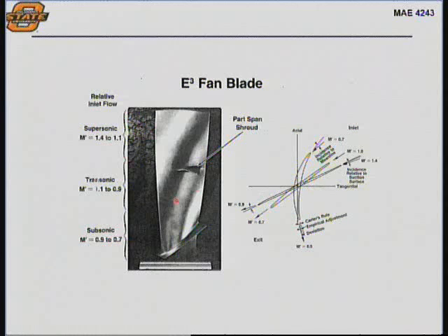So this fan blade starts out with a big fat thickness at the hub. As it moves higher to the tip, it changes its stagger angle dramatically and also gets much thinner. You can imagine interpolating what this looks like going from the hub to the tip, and how it changes in thickness and angle. This is just the fan blade. So those fan blades see a radically different flow field just along their span. You need to appreciate that.